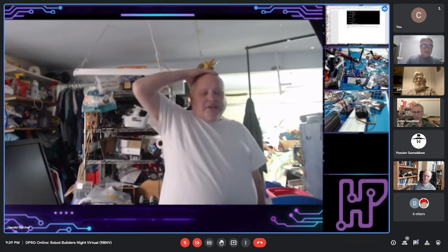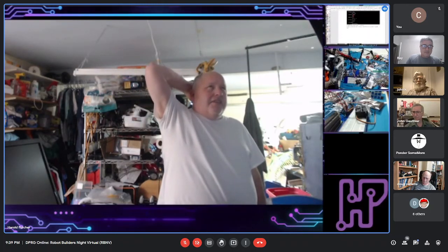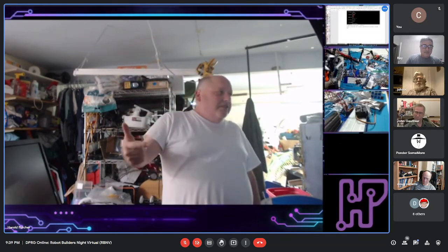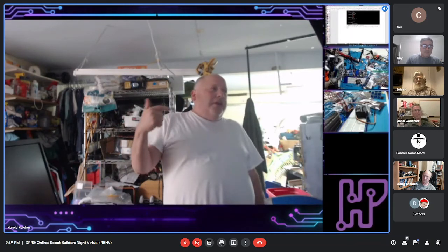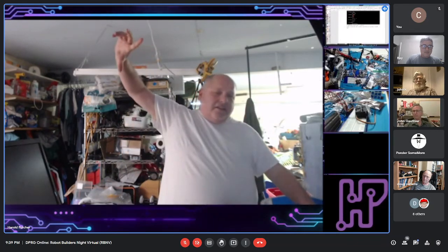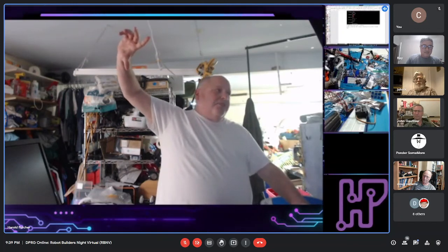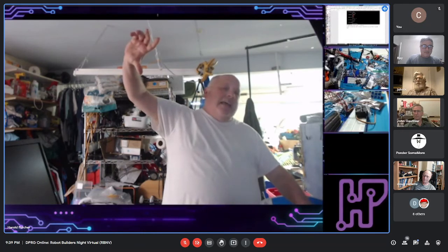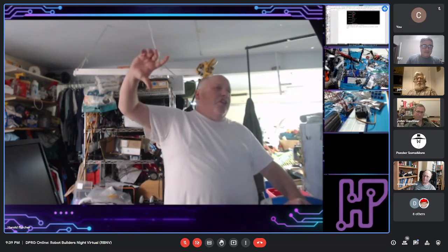So you get this big block of stuff, but it makes its own support as you go. A couple of things with that printer: the stuff that doesn't get fused, they reuse 80% of it in the next one that you do. And one of the other weird things, because the cooling matters on this, you're getting a big block like this of stuff, so you're printing hundreds or thousands of those little things at the same time. And it has to set for as long as it took to make.